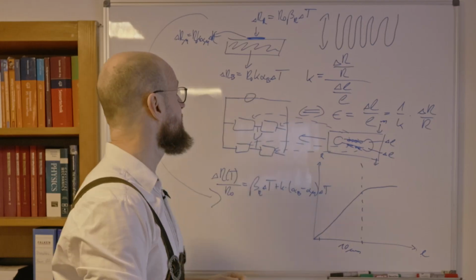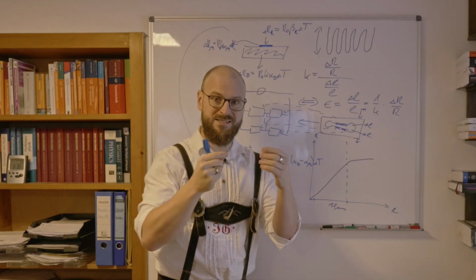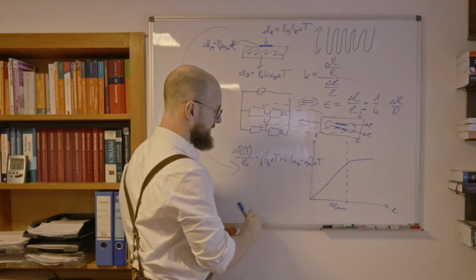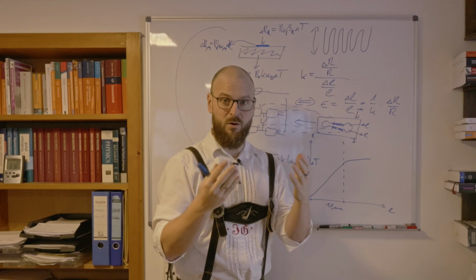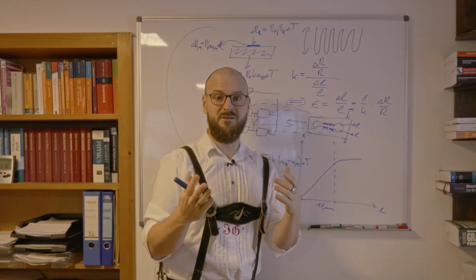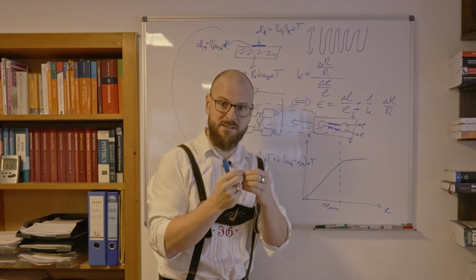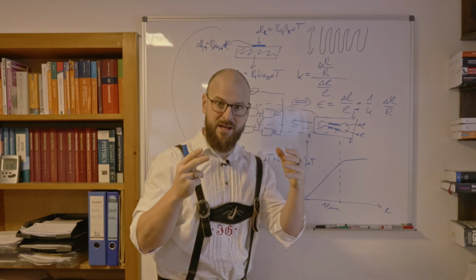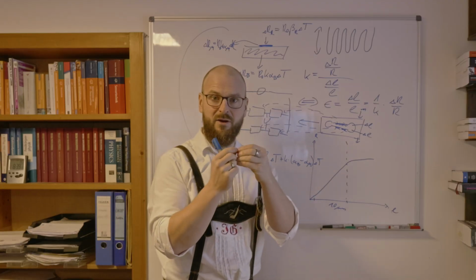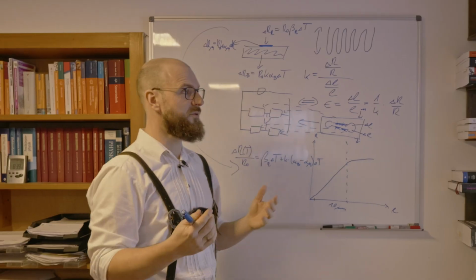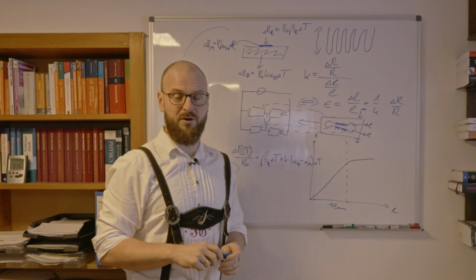considering the resistance. Why is that so? So the component we are measuring on elongates, and that means the strain gauge gets stretched. That means the resistance rises over here. Now, on the other hand, when the strain gauge gets warmer, it also elongates, but does not change its resistance due to the mechanical deformation, because it gets enlarged in every direction due to the temperature. That means that is in the different direction. The elongation, the enlargement of the strain gauge due to the temperature works in the other direction than that of the component itself.